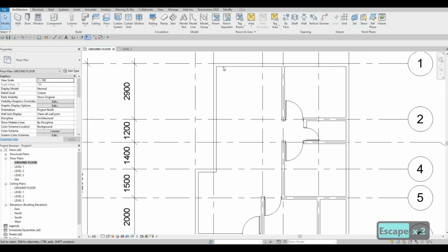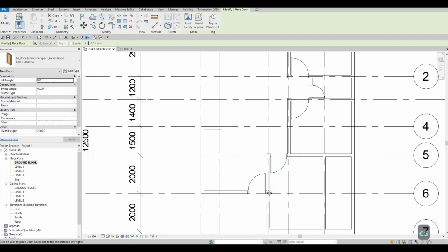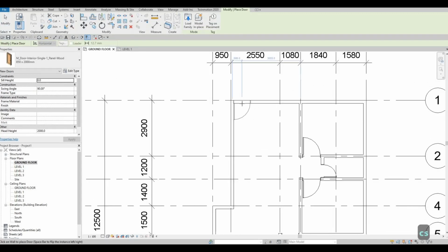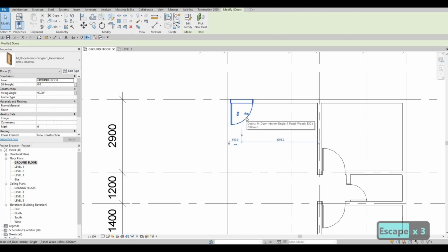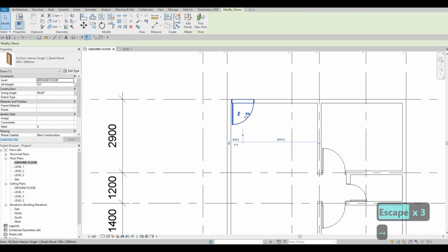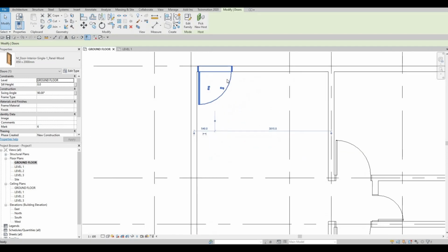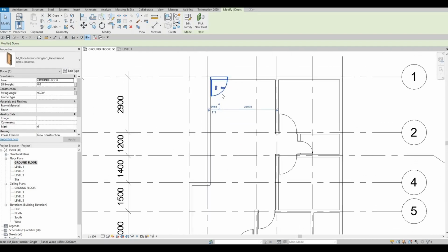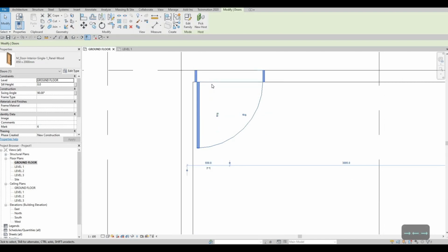By the way, we're gonna also add in a door right here. We could use the 850. So I'm gonna click here and then type in CS, and it will add the same door right here. And then just click it again to nudge it in place. So you can use your arrow key to just simply move it around like that.